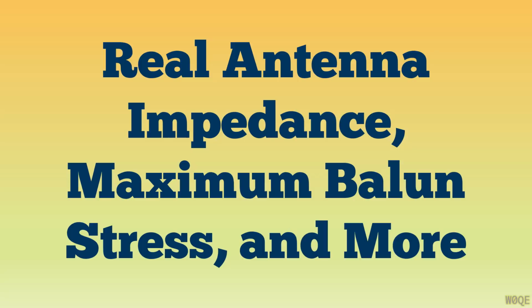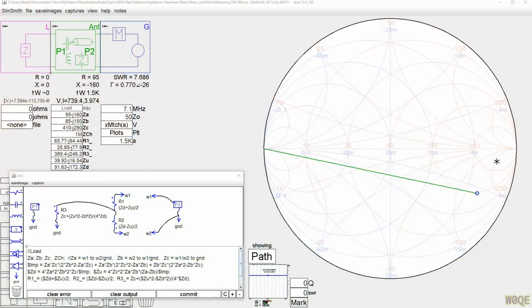The previous video, number 81, showed that the heating effects of a balun were directly due to the common mode voltage across the balun. There is also an indirect heating from the wire due to the total current flowing in the balun, where some percentage of that heat increases the core temperature. This is nearly all from differential current, since the design of the balun is to reduce common mode current.